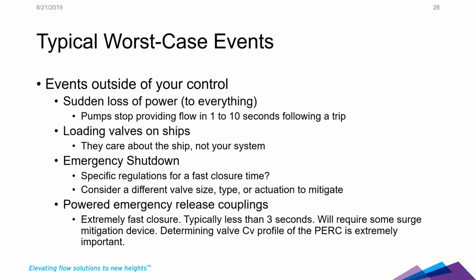If you do, you're kind of working within a fixed timeline. You can't maybe say, well, this would have a better response if we just extended our valve closure. Sometimes that's not an option. You have to do something different. You have to do a different valve size. If you choose a smaller valve, you might be able to start controlling your flow sooner.